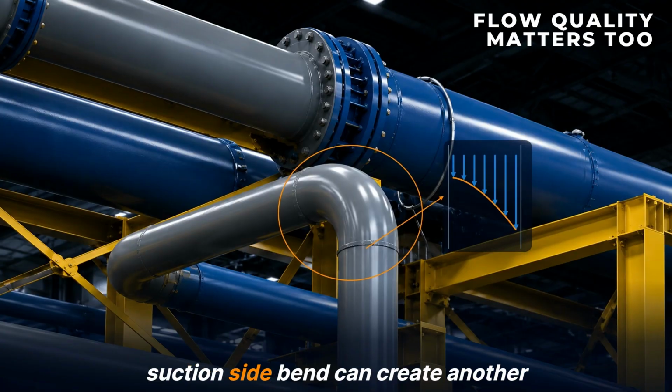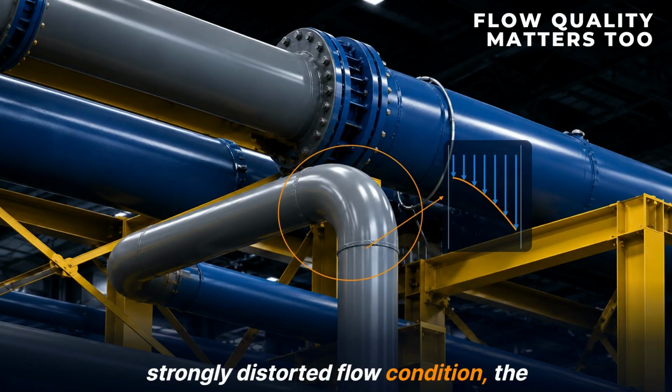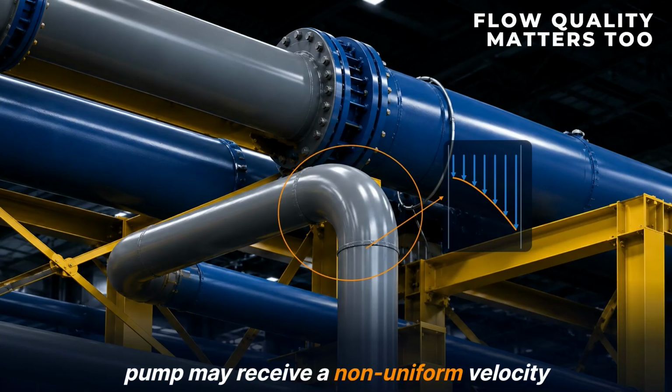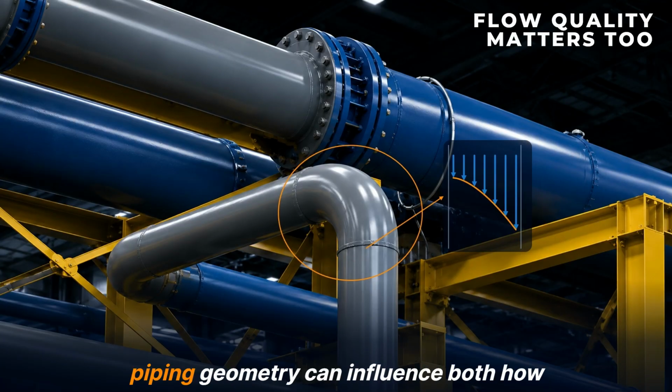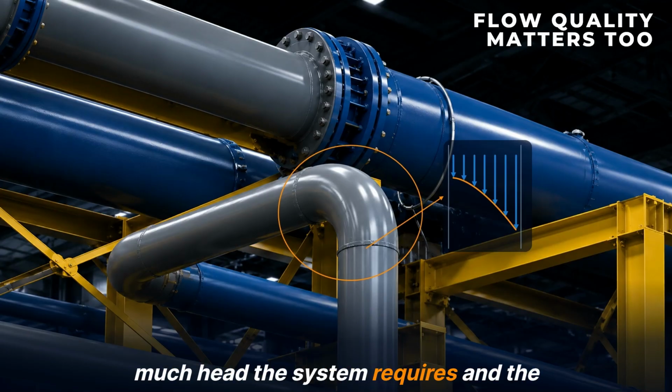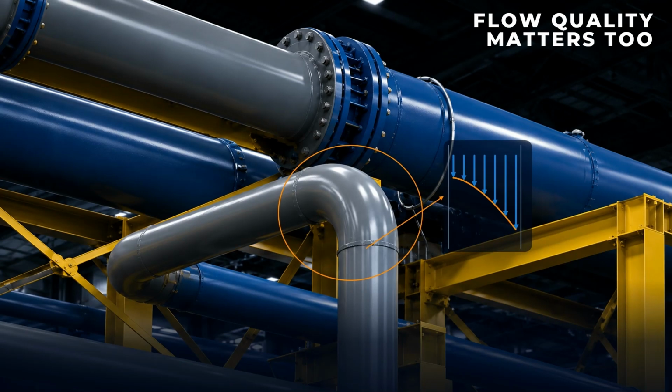But a suction side bend can create another problem as well. If an elbow is located too close to the pump inlet or creates a strongly distorted flow condition, the pump may receive a non-uniform velocity profile or unwanted swirl. So the piping geometry can influence both how much head the system requires and the quality of the flow delivered to the pump.